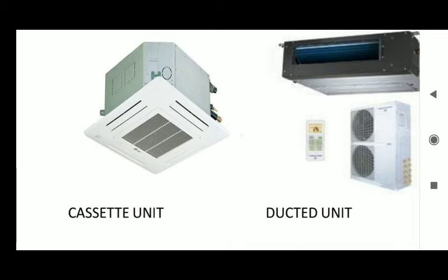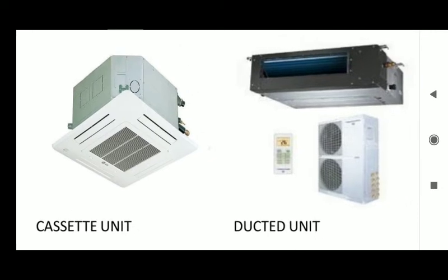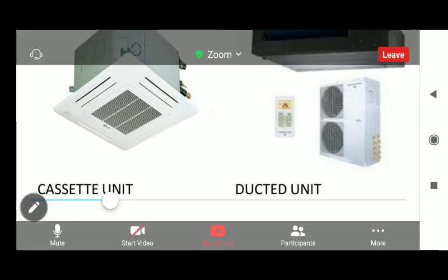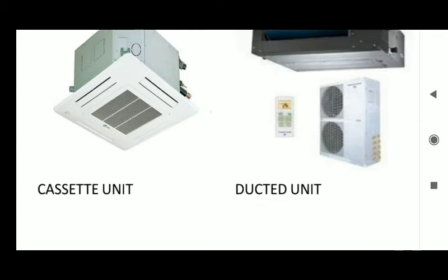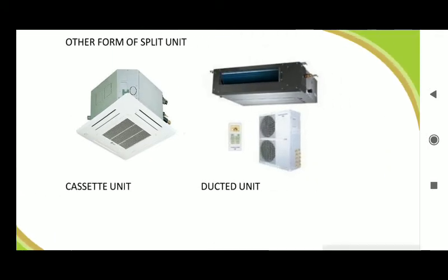There are some that will tell you they don't want cassette units because maintenance is always an issue, or with time the white surface will turn milky. They want something hidden, so those ones go for what they call a ductable unit. The ductable unit is always in the ceiling and it is ducted out to where it needs to cool. Sometimes these outdoor units, you see them in double volume, depending on the heat load they need to take care of.